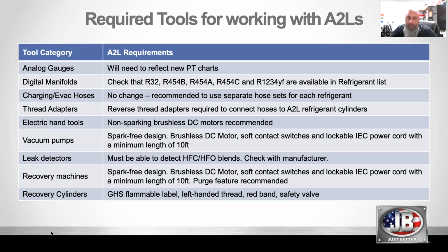One thing I did want to point out, though, just to put emphasis on it: if you notice on the vacuum pump and the recovery machines, he's got on there, and I know this to be accurate, they want a minimum of 10-foot cord. Yep. So we've got some equipment out there. Even if you are using something that is old reliable to you, if it doesn't have that 10-foot cord, and if it does get unplugged, we just want to do everything we can to prevent a spark, because strange things happen sometimes, and anybody who's been out in the field knows that sometimes you get just the oddest thing happen. You're working on one unit and there's another unit next to you that's leaking and you don't even notice it, right? We don't want to create a spark. So absolutely, it's always best to get in line with what we need to do. We're all professionals, and we should be acting as such and be properly equipped to do the job.